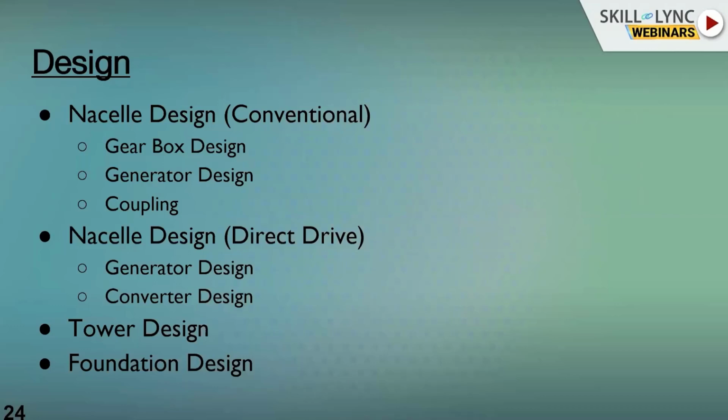Foundation also nowadays, if the available land has sufficient bearing capacity, then they will go for a normal foundation. If the land is near a water area or the soil condition is very poor, then they will go for piling and also raft foundation. This depends upon the availability of the land.